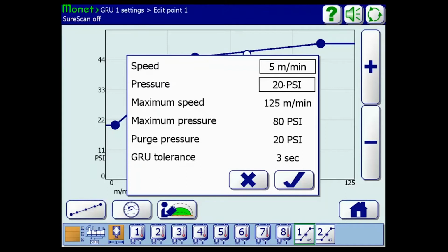One thing that's important to understand about this is you're not looking on this screen at glue pressure. You're actually looking at the air pressure going into the tank. So we're actually regulating air pressure to the tank. We are not actually reading the actual glue pressure coming out of the tank. We're just referencing the commanded air pressure going into the tank.